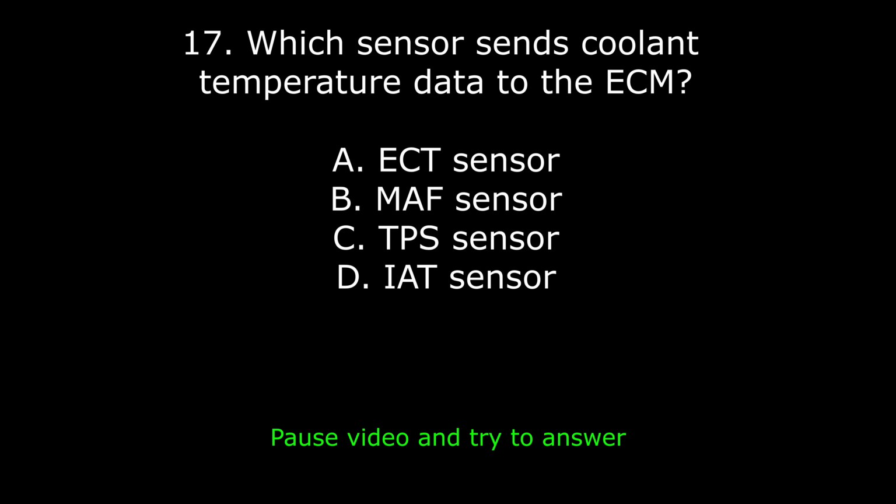32. When handling an HID bulb, why must you avoid touching the glass? A. Finger oil shortens bulb life. B. Causes color change. C. Can cause arc flash. D. None. Answer: A. Finger oil shortens bulb life. Explanation: oil causes hot spots on quartz glass, leading to premature failure.